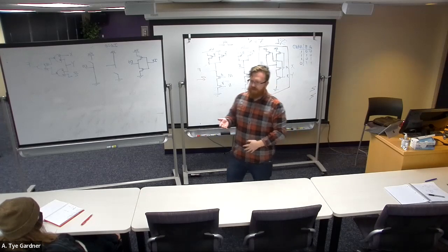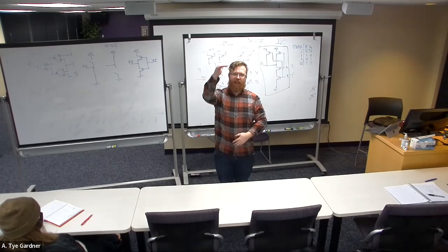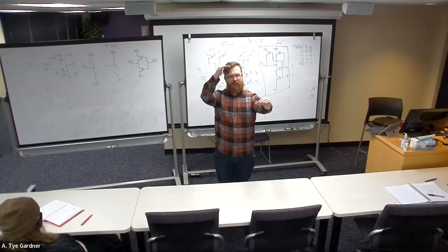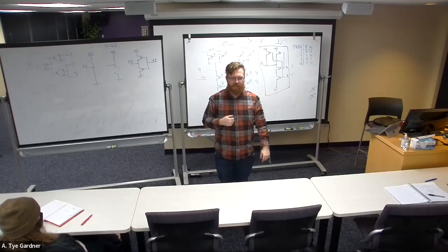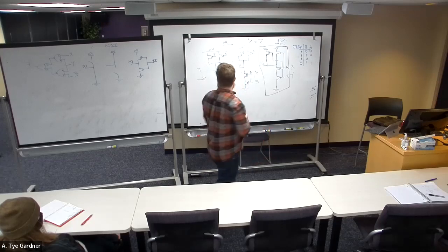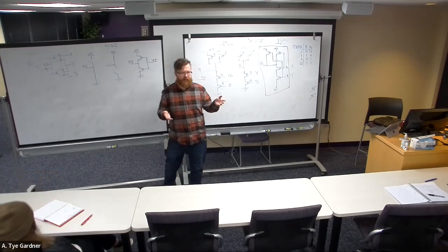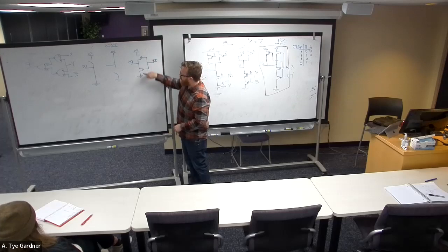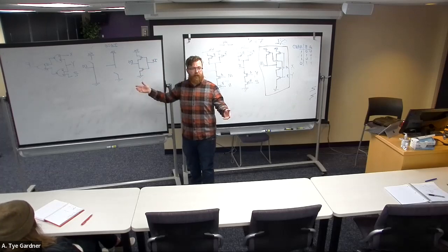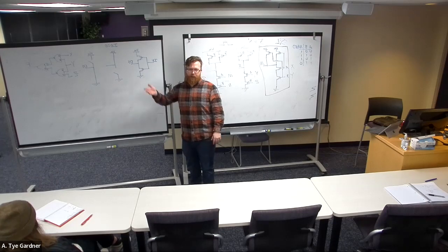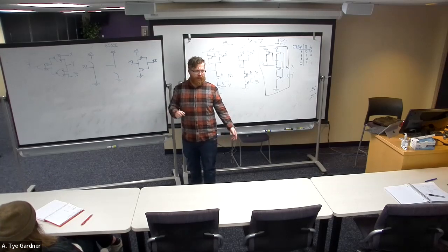And the other way of saying that is if I'm trying to send a string of ones and zeros and I have a 1 and you put a 0, then what is the voltage on that wire? Because over here it's a 1 and over here it's a 0. And what happens is you break both devices, right? Because if I close both switches, if I designed a bad circuit that closed both circuits, that means I have direct connection from power to ground with no resistance between. We have Ohm's law that says the current is proportional to the voltage divided by the resistance, right? V by R. R is 0, current is infinity, which means something breaks.